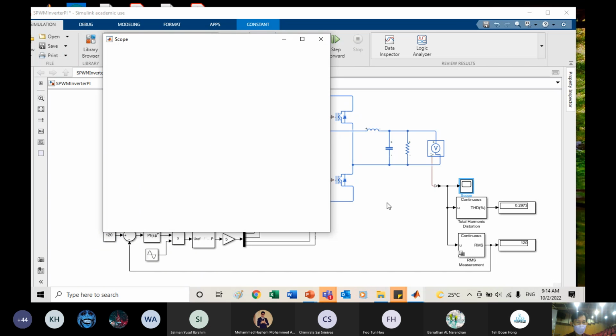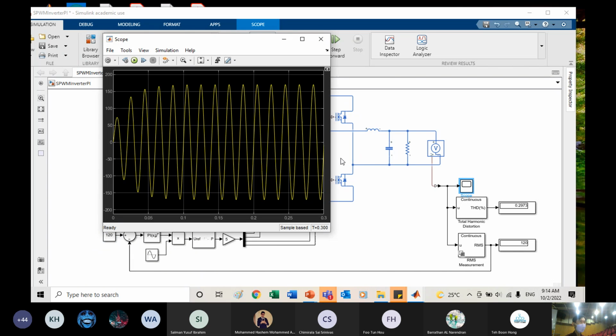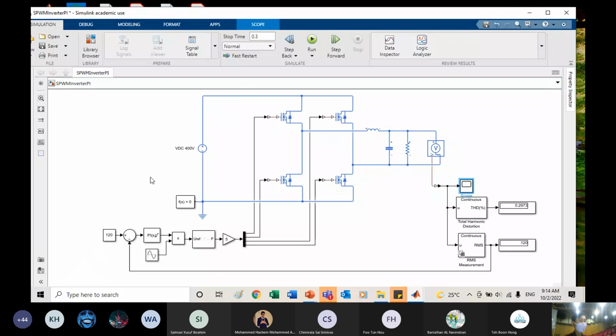That's why you see inverters that let you set which country or region you are in. If you don't use any feedback, the voltage is fixed, you cannot set it. So this is how you control. Now I can bring this to the US and still use it without changing to a new inverter. It's just a control setting here.